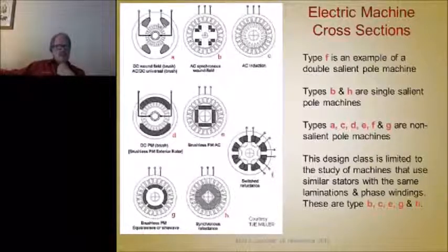armature. Now, what's interesting to note, even by looking at this picture, is down here we have a permanent magnet version of this. Here's a permanent magnet version of that. Instead of this wound electromagnet, North Pole and South Pole here, we have a permanent magnet. Now, there's no wires connected to that, so the flux from this permanent magnet is fixed.